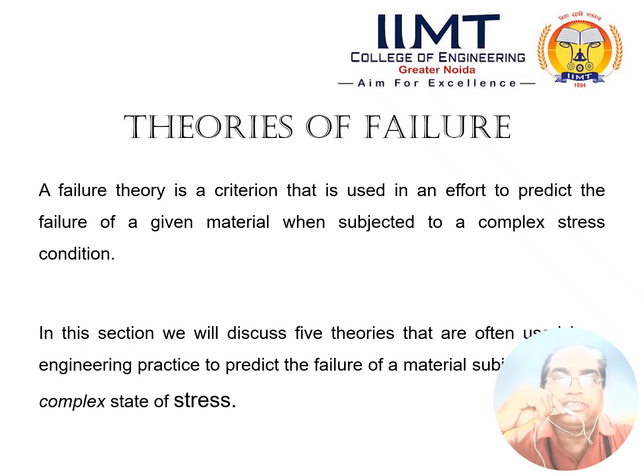As we can see on the screen, the failure theory is a criterion that is used in an effort to predict the failure of a given material when subjected to complex stress conditions. So in this section, we will discuss five theories of failure which are used in engineering practice for making mechanical engineering components that are subjected to a complex state of stress.